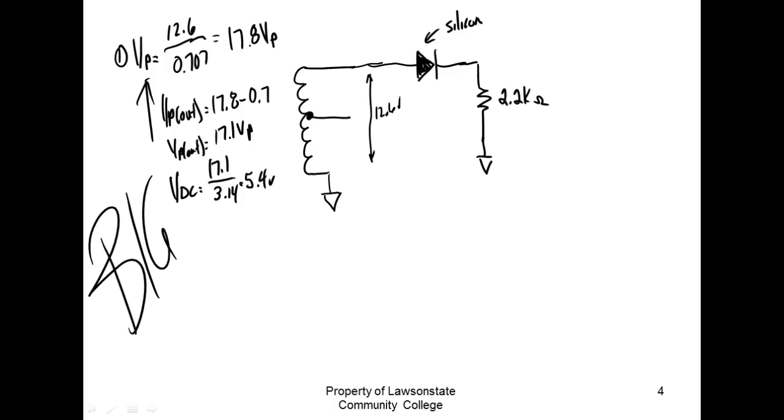Now what I'm going to do is put my capacitor across the resistor out there. That's where we want the unregulated DC, right? So I'm going to put my scope back out there, and let me get rid of channel 2. I'm going to put channel 1 over here, and we'll turn channel 2 off. Okay, so there's my DC.